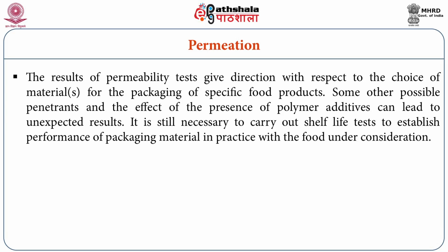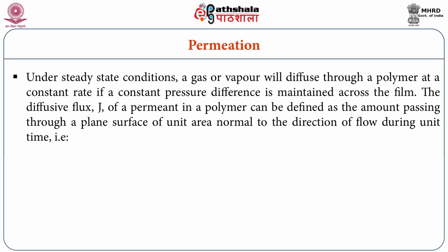The results of permeability tests give direction with respect to the choice of material for the packaging of specific food products. Some other possible penetrants and the effects of presence of polymer additives can lead to unexpected results. It is still necessary to carry out shelf life tests to establish performance of packaging material in practice with the food under consideration. Under steady state conditions, a gas or vapor will diffuse through a polymer at a constant rate if a constant pressure difference is maintained across the film.